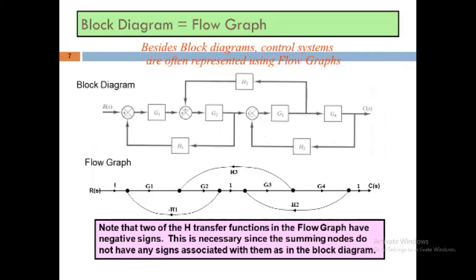Here is the definition of the transfer function: it is defined as the ratio of the Laplace transform of the output to the Laplace transform of the input under the assumption that initial conditions are zero. Whenever we take C of S as an output and R of S as an input, let us consider the initial conditions are always zero.